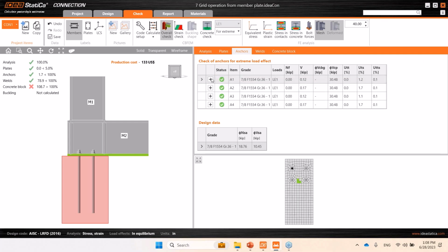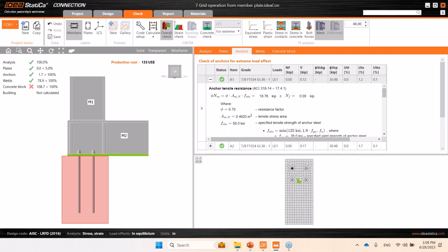Somebody was asking about recommendations for when they want to use mechanical or adhesive anchors. So I thought it might be worth mentioning the Hilti integration that we're working on, and anything else you'd recommend for that process. Yeah. I won't say a time frame because I'm not sure about it, but at some point we'll be able to transfer the information from Hilti to IDEA StatiCa to bring those specific details that you need for the anchors. Perfect. And so at this point, if I wanted to use a mechanical anchor, I'd run my design in here for a base plate and then design my anchor in a different software using the forces I came up with.